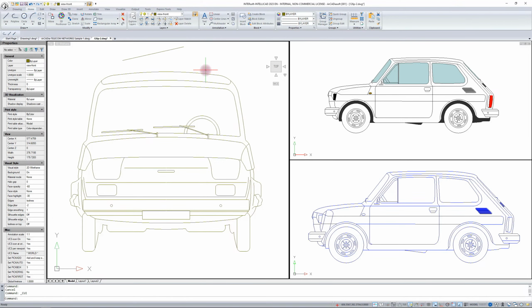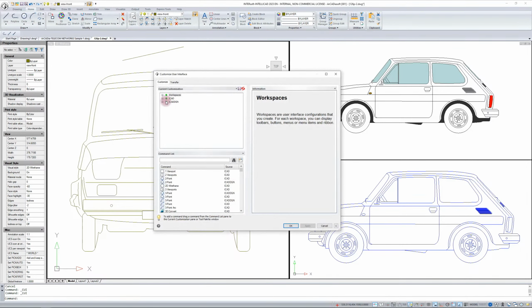I will show you such an option which shows at what point the program already warns us that you definitely need to do this refresh. But sometimes it comes in handy just to redraw something to check if everything is in place. So I will set it up for myself under the F5, and later I will show you how it will work. And now we're going to do a similar thing with alias. So here we have letter L. But we already know that this is the letter that stands for line.